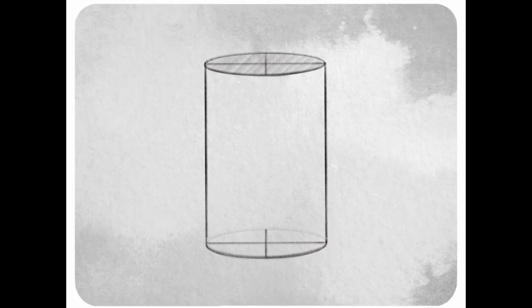If the center line goes too far to the side, one way or the other, or too far up and down, you have a ton more space on the top half than the bottom half, for example, on that ellipse, then you may find that you run into some problems. And that's a clue that you want to adjust that to have those quarters all be equal. And then when you're done figuring that out, you can erase those guidelines and just leave the elliptical shape.